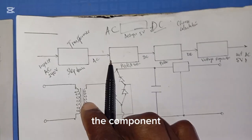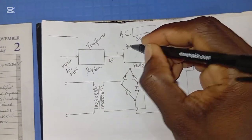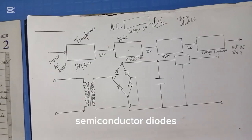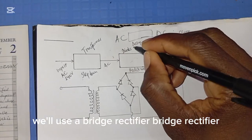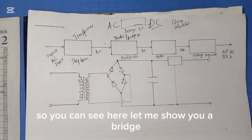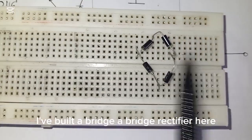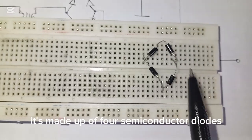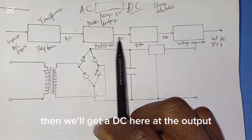The components which allow us to rectify AC to DC are semiconductor diodes. To achieve this successfully, we'll use a bridge rectifier. Let me show you: I've built a bridge rectifier here. It's made up of 4 semiconductor diodes. Then we'll get a DC at the output.